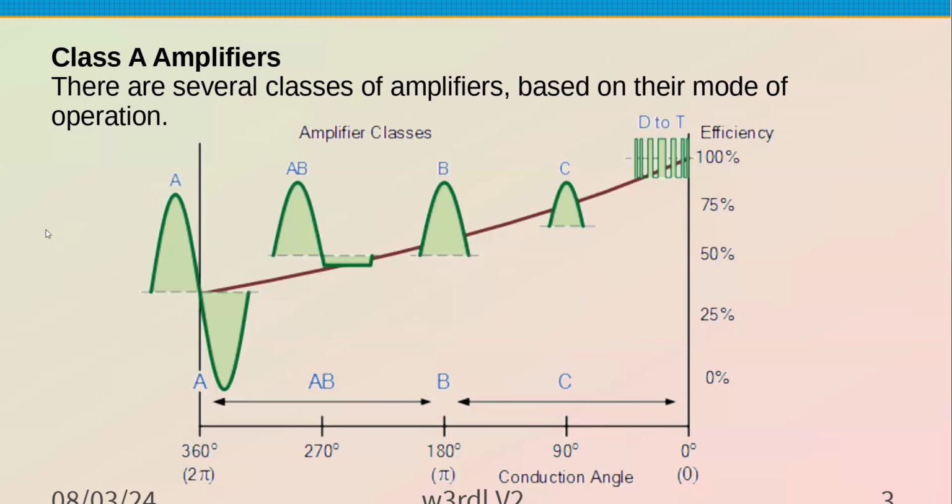Letting the output amplifier on your transceiver be separate, well, you could do that and have a little more distortion. So it depends on whether you want to meet the FCC requirements for the third harmonic. Is that 40 dB down or something in that range.